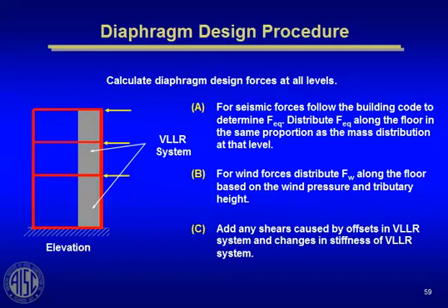Okay, one important thing to remember is that the way a diaphragm feels forces from wind and the way it feels forces from seismic are totally different. For seismic, the code actually has diaphragm shear equations and tells you how to distribute the diaphragm shear from the field of the floor into the diaphragm. And as you might expect, it's proportional to the mass of the floor, or it's a function of the mass.